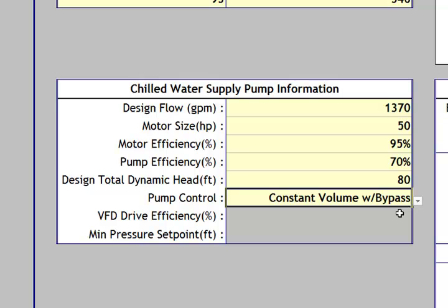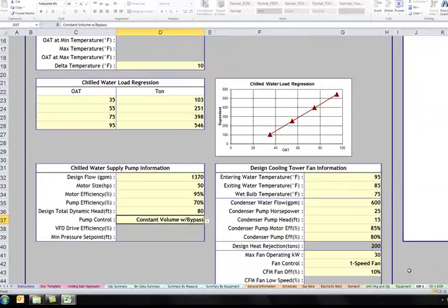For systems with multiple pumps, you may need to either combine the power draw of these pumps, or if the pumps operate at different times, such as 2-pump operation at hot outside air temperatures and 1-pump operation at all other outside air temperatures, namely cooler outside air temperatures, you may need to define multiple chilled water plant scenarios on the Equipment tab and look to the bin data summary for the savings.